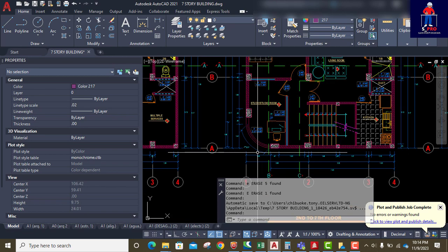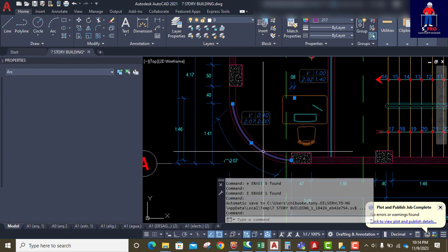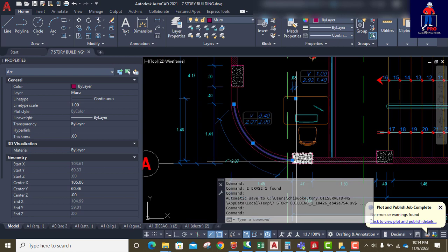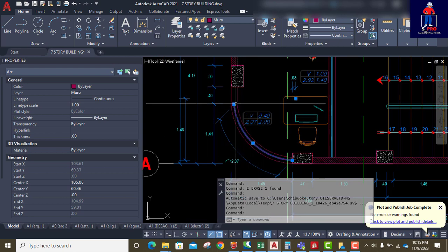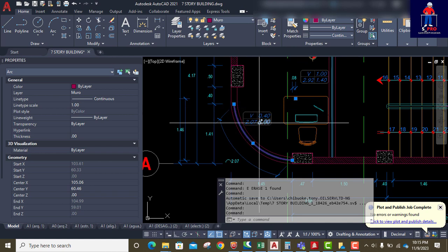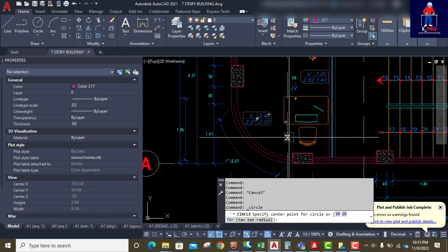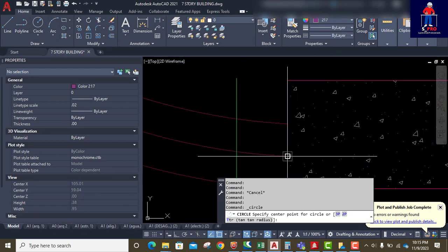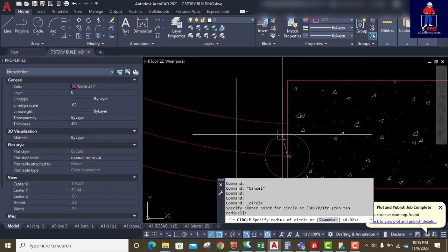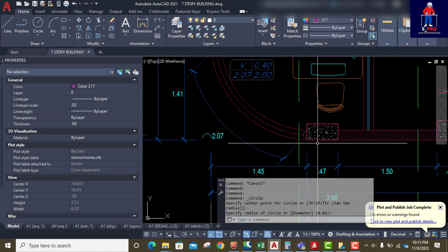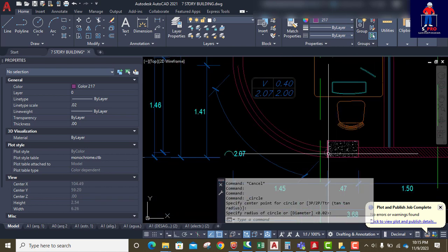So this architectural drawing, this is the set. So we need to create some nodes along this curve and model it in our model in Staad.Pro. Then use normal beams to join the lines. So what I will quickly do is I'll click on this circle. I'm going to draw a circle here. So this is node number 1, which of course is already existing in the model. So I'm going to create more nodes here.